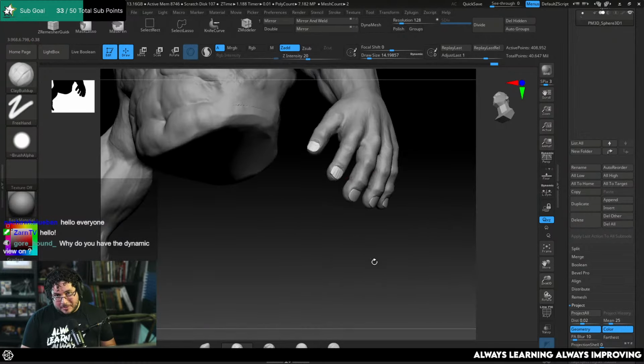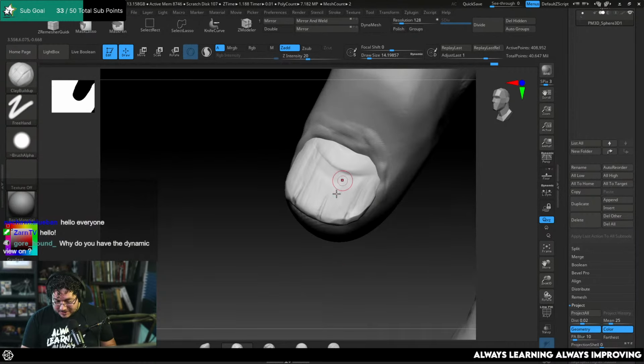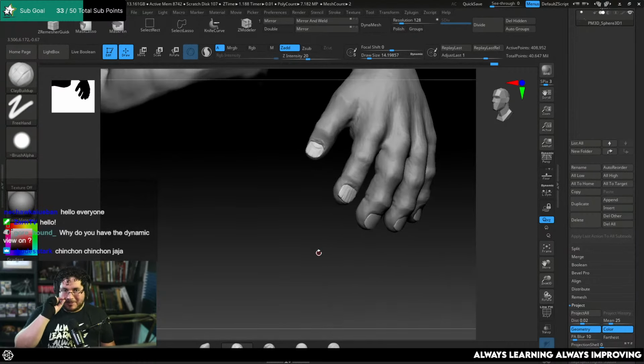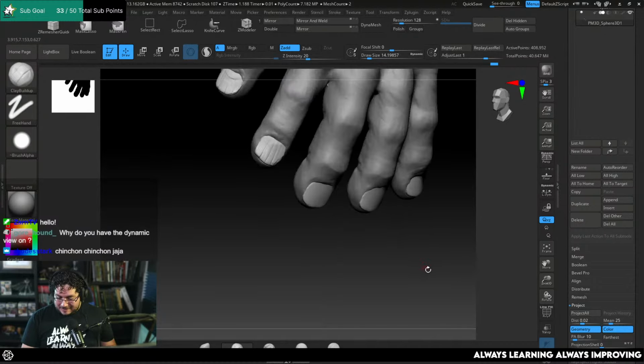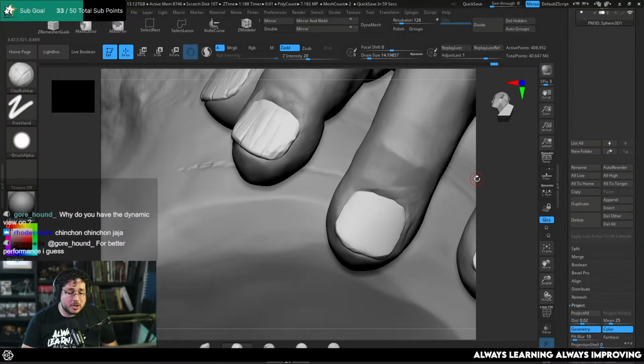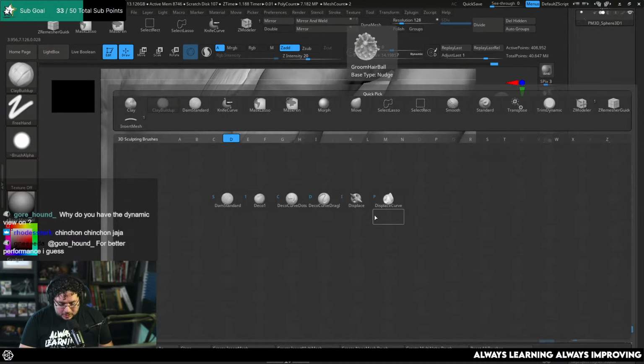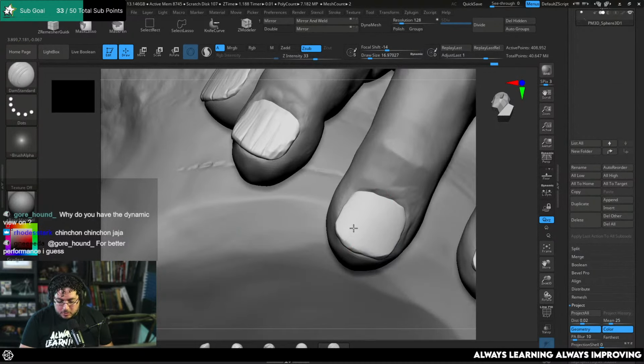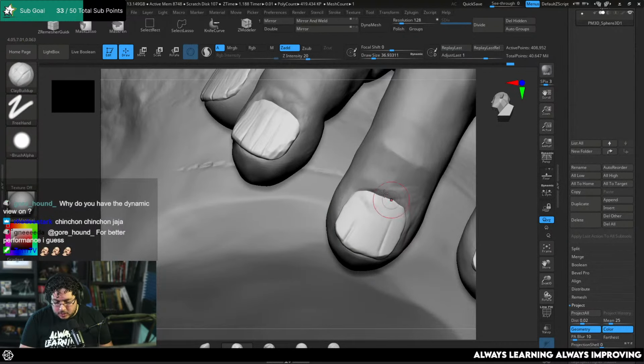And you know what the funny part about this whole thing is, guys? We're spending 30 minutes sculpting these nails, and at the end, they might just have like 20 pixels of texture resolution. So, yeah. That's another quick efficiency tip that I can share with you guys. If you know that you're going to be working on a project with very low resolutions, like mobile or VR or things like that, you don't need to spend an incredible amount of time here on the sculpting stage, because a lot of that stuff's not even going to be seen, or you can just solve it with a nice texture in Substance. So that's where the experience comes in.